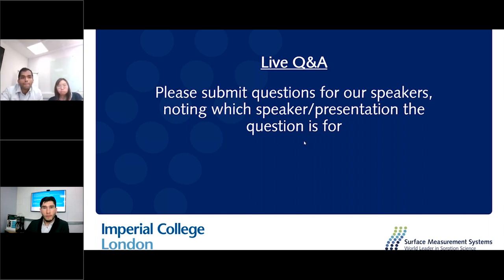Hassan, this is from Sean McIntyre. They ask, when looking at temperature effects on the micro and macro pore diffusion via ZLC, how are you accounting for the heat effects from adsorption? That's a good question. One of the reasons we reduce the size of the sample, as opposed to using a whole pellet, is to reduce the heat effects in the experiment itself.